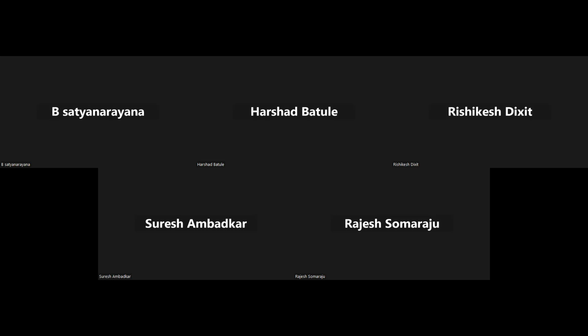Sir, Rajesh is here. Yes. For compressors, they are calculating the FAD, na? FAD is P2 minus P1 by P naught. So in the question, they are giving the gauge pressures. Okay. So the same can be converted into absolute pressure, right? Right. So sometimes they are using this and sometimes they are not. Is it mandatory to convert gauge to absolute or is it not required? All the pressures have to be in the same format, either absolute or gauge. Whether absolute or gauge, all have to be in the same format. Okay, okay.